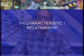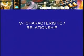In electrical engineering, of course, one talks about this and the other relationship for the resistor as a VI relationship or VI characteristic. So the VI relationship for an inductor is given by V equal to L di/dt. If I is in amperes, and the time is measured in seconds, so the rate of change of current is measured as amperes per second, and if the inductance L is in henries, then the product L di/dt will give you the voltage in volts.